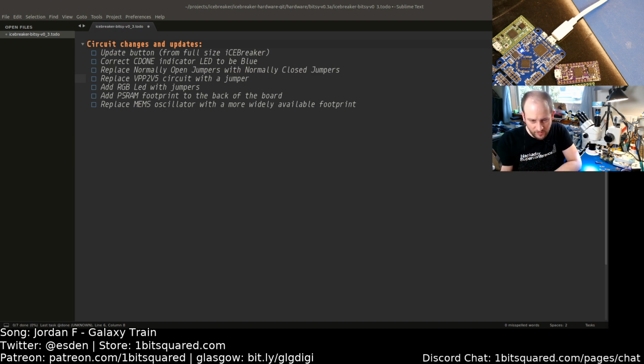It has additional differential pairs. The connector pins are quite dense. It is an increase in manufacturing difficulty to use the finer pitch connector pads on the board. There is also a coarser connector that has only the USB 2.0 pins.